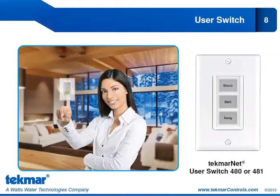Now we can use a user switch 480 or 481 and configure it for storm, melt, and away, so that at the touch of one button we can put our snowmelt system into the storm state after hearing on the news that there is an expected snowfall coming. Or if we are manually operating our system, then we can push the melt button and trigger a melt cycle to occur in our snowmelt system.